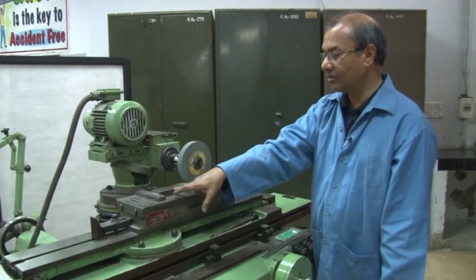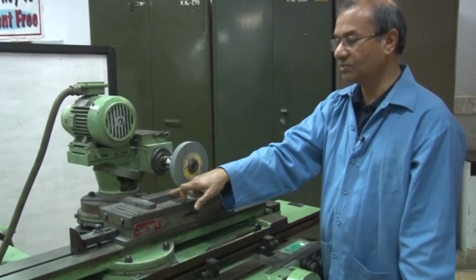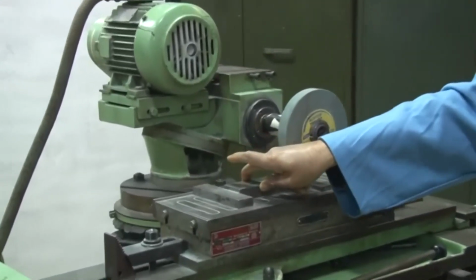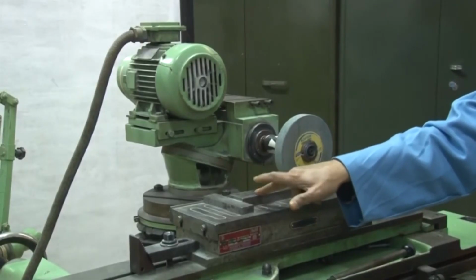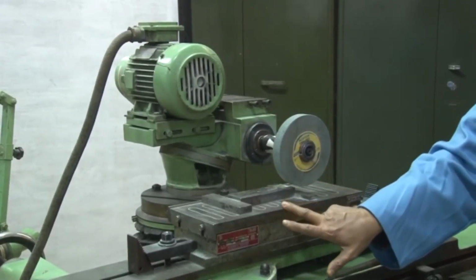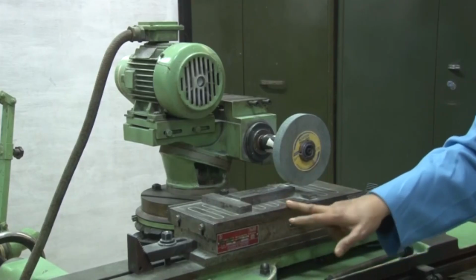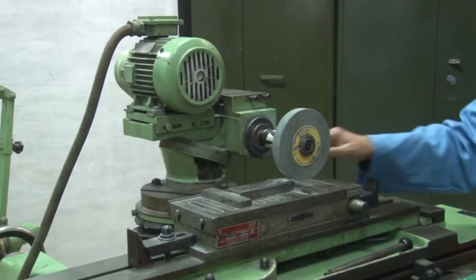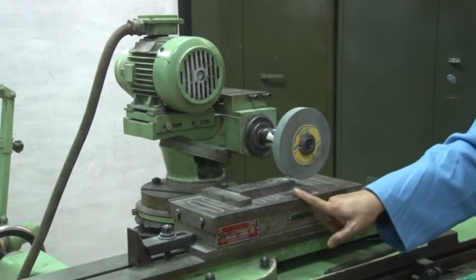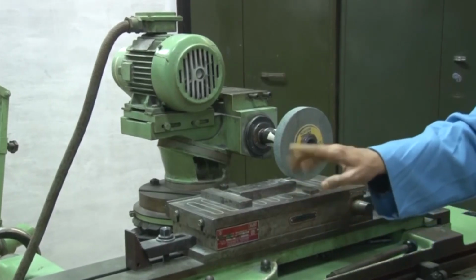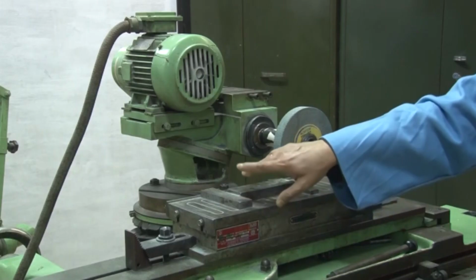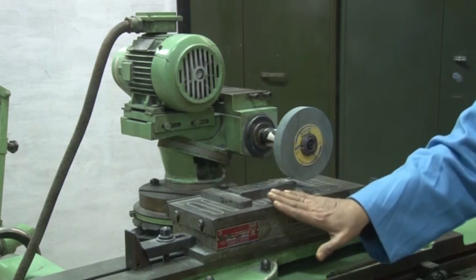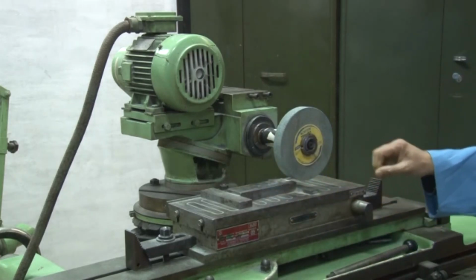This is the workpiece, and this workpiece will be ground. Surface grinding of this surface will be made, and this is a ferromagnetic material, and this workpiece is mounted on a plate which has a magnet. This can be demagnetized or magnetized depending on the handle. There is a handle, and this handle will make this magnetic or non-magnetic. When the clamping has to be done, this workpiece will be clamped very rigidly. You can see that it is very rigid because it is a very strong magnet.